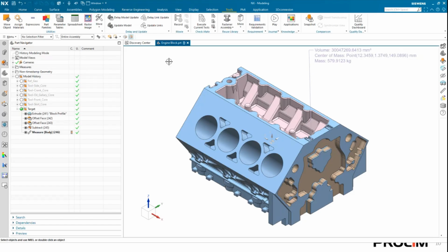Now, you might have the burning question of how do I do this if I have Teamcenter integrated? Well, I came prepared this time. I asked one of our application engineers that works with Teamcenter, and he told me that there is a module called IMM, or Integrated Materials Manager. And that is what you would need to use to allow Teamcenter to begin managing your material library rather than having a shared folder or a shared drive.